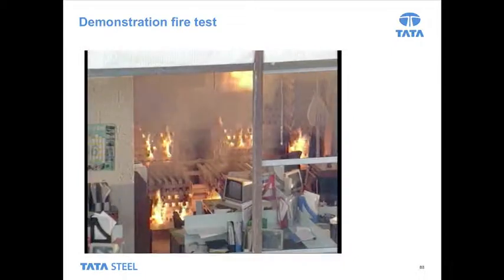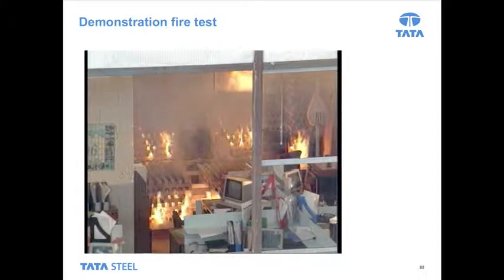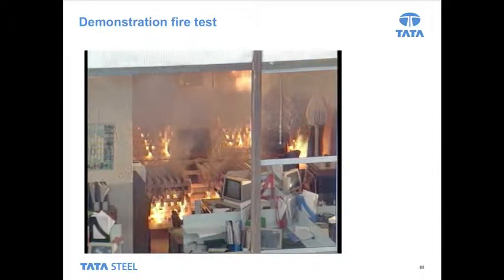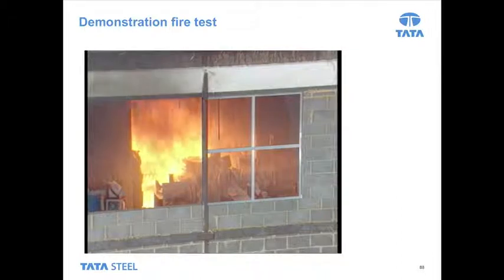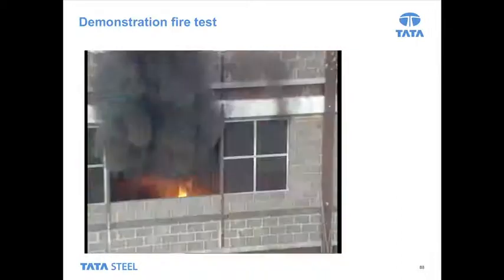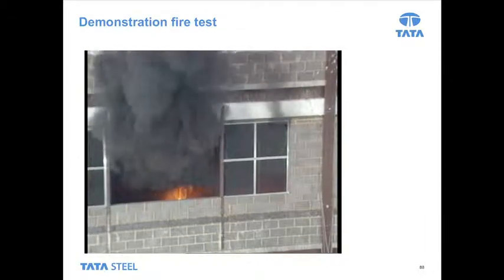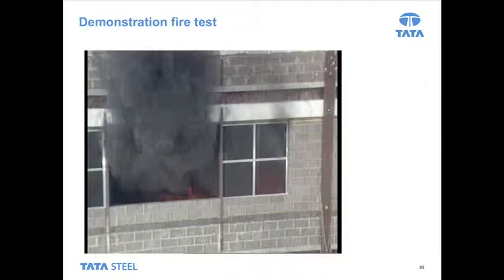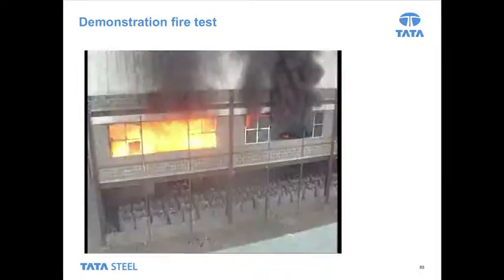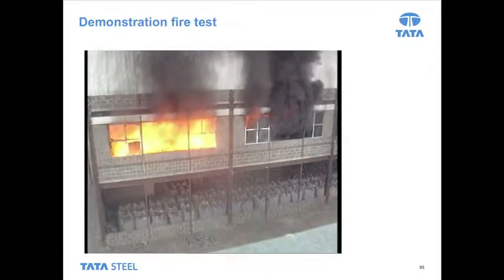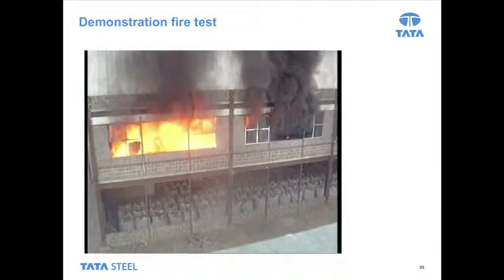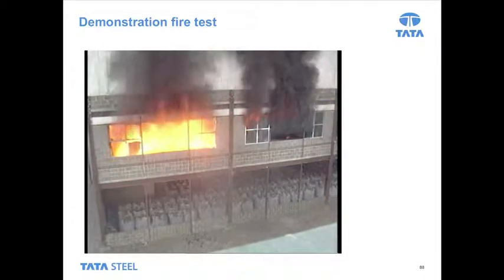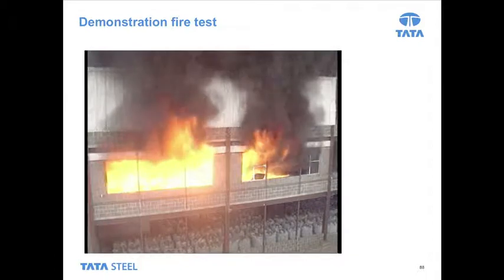So this is a short video of what a natural fire test looks like. And it's customary, as you saw, to send in your most expendable member of staff to light the fire and get it started. I don't know if you saw that at the beginning there, but the steel members were unprotected. The only thing that was protected here were the columns. So the beams, and that's all of the beams, and the floor deck itself were left unprotected, so no fire protection to those at all.